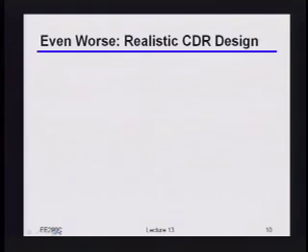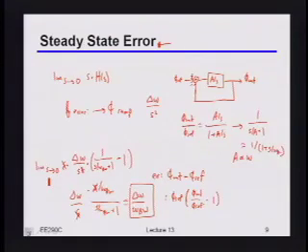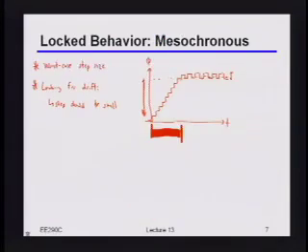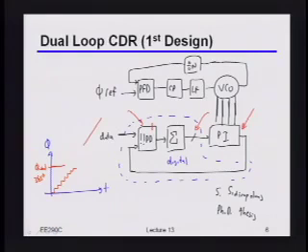Now, there's one thing that is going to make life actually a little bit worse, which is that, as I was mentioning before, those updates are coming at a pretty high rate. If I'm running this thing at, let's say, 12 gigahertz or 12 gigabits or whatever it is, I'm going to be getting these updates at a 12 gigahertz rate, or 12 gigasample per second rate. And that's probably much, much faster than I really want. That's probably much more data than I can really effectively use, or at least building the digital processing to run at that speed will probably cost me quite a bit of power.